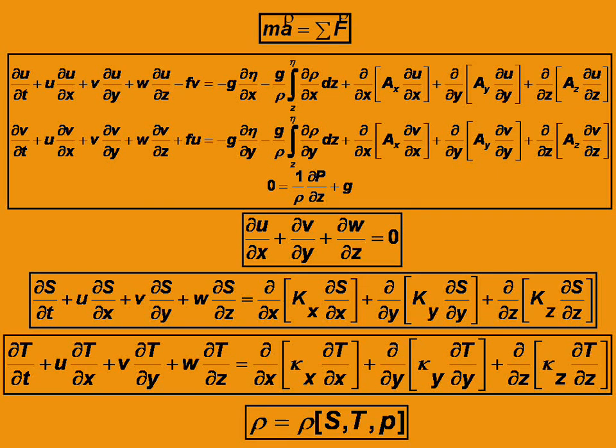And people have been developing in the last decade or so non-hydrostatic models, where they represent the vertical component of the flow in its true fashion. So can you imagine when one of these acceleration terms, or these frictional terms, can be larger than gravity? That is a non-hydrostatic approximation.